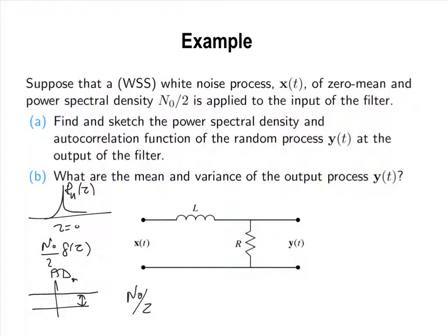Typically, noise is modeled as a Gaussian random process, which means that the value of the noise, if you say, for example, that the variable n represents the noise, and this n must be also a function of t. That's why we call it a random process, right? But n itself is a random value. Remember, we described random process at the start of this chapter. It has randomness in its value, and it is a function of time at the same time, right?